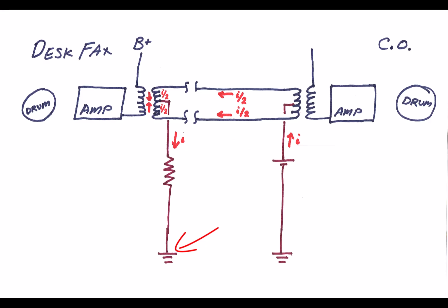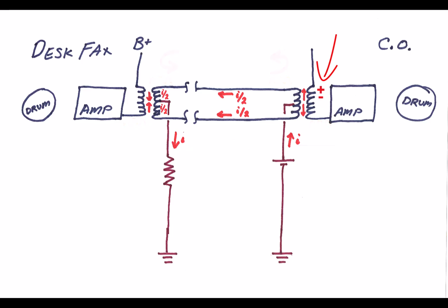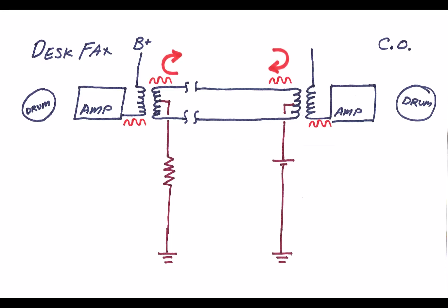But, and this is key, of course, all the currents are additive, and since the two current halves of the DC current are going in opposite directions in their windings of the transformer, their influence on the amplifier winding is canceled. This top half current creates a DC voltage in the amplifier winding with the top being positive, while the bottom half current induces a DC voltage in the winding with the top being negative. So these two DC currents exactly cancel each other out. Only the loop current is picked up by the amplifier, and that common mode DC control signal is not detected by the amplifier.